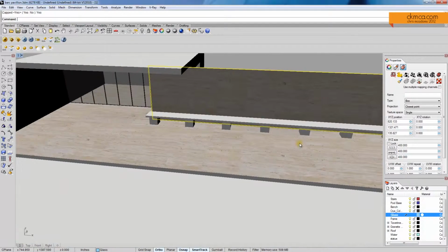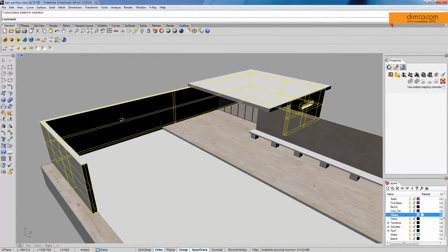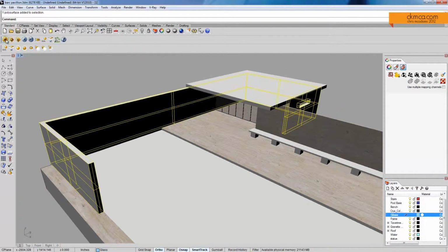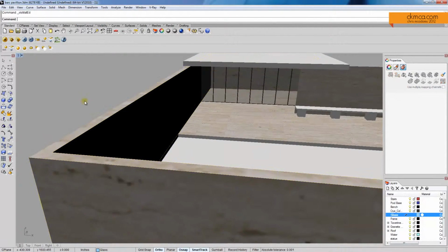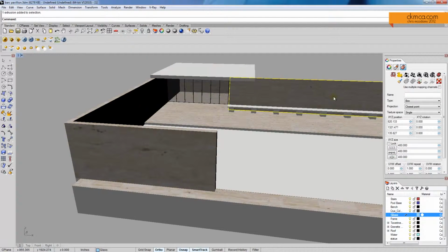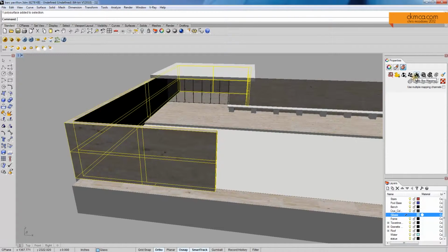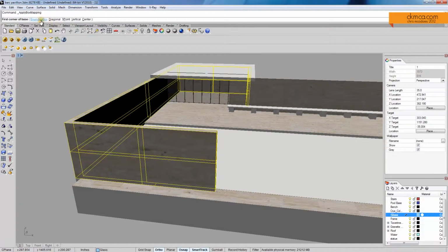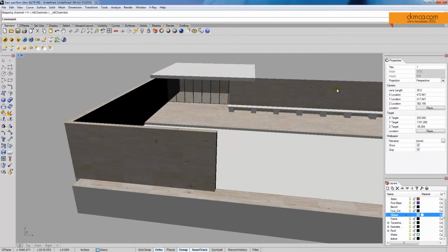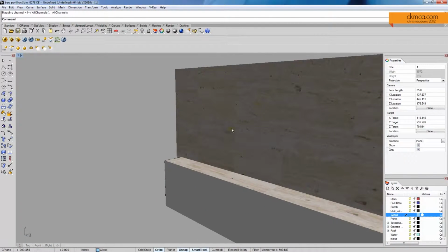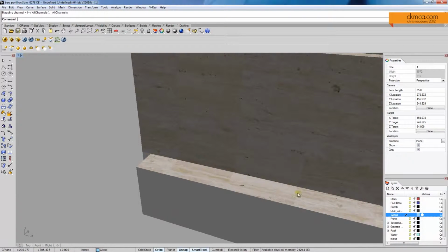So this seam runs all the way down onto the floor, and that's an important part of the pavilion. When I take this second wall that wraps all the way around, I'm again going to go to materials, right click and apply the material. And what's nice is I can match it. This is using a bounding box with 400, 400, 400. I'm just going to right click on this guy, say I want a bounding box, say yes, bounding the world, cap it yes, and then Rhino 5 gives me the ability to match properties. So I'm going to match my mapping to this existing one, and now you can see I have everything just as I did before, and it lines up.